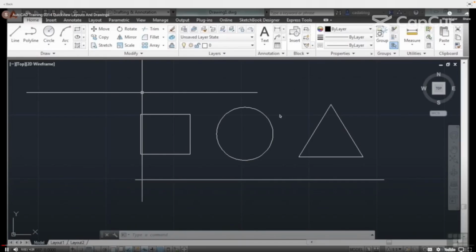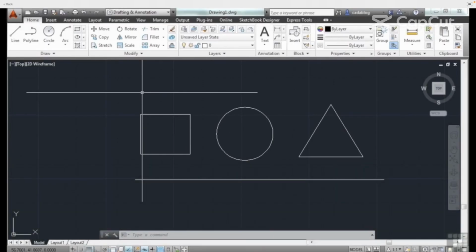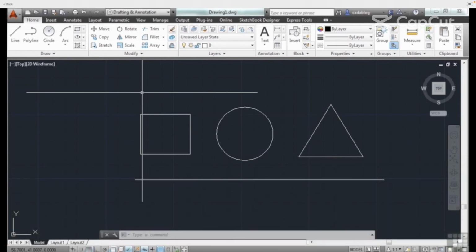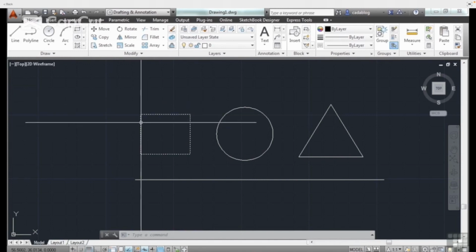When you work with AutoCAD, you will often find it useful to have more than one drawing file open at a time. And some of those drawings will have multiple drawing tabs or paper space tabs in them. Navigating through that mess can be difficult and sluggish. How do you know which drawing you need or what tab you need, especially if they aren't your files? A very quick method of switching through open drawings is by pressing Control and Tab at the same time.